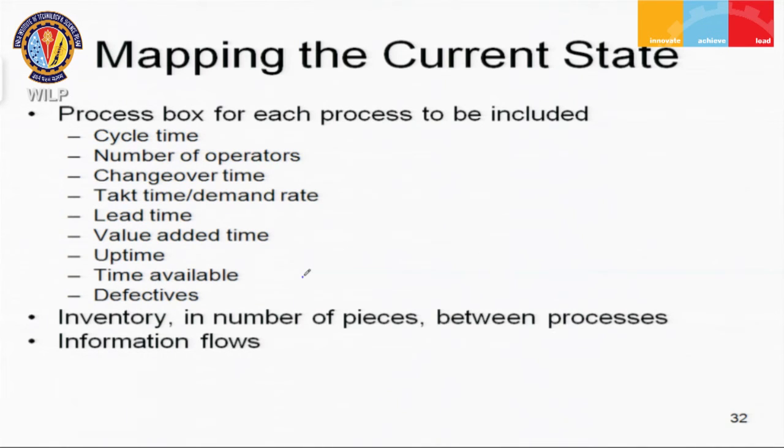What is the lead time? What is the value added time? That means the actual time to complete the process. What is the uptime, which is a function of breakdown frequency for that particular piece of equipment. The total time available. Are you working one shift, two shifts, how many hours per shift? And generally, what are the percentage defectives that are being produced on this particular machine?